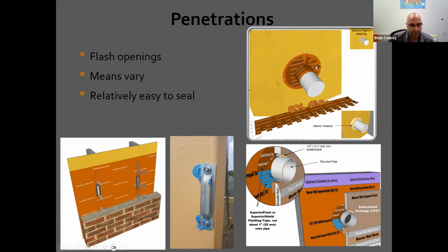I usually show this mainly because something like this is a 6-inch diameter wall penetration pipe. If somebody forgets that hole and then they have to punch through the wall, remembering and showing what that really looks like around that 4-inch or 6-inch piping is helpful, as well as a sealant possibly on the interior side.